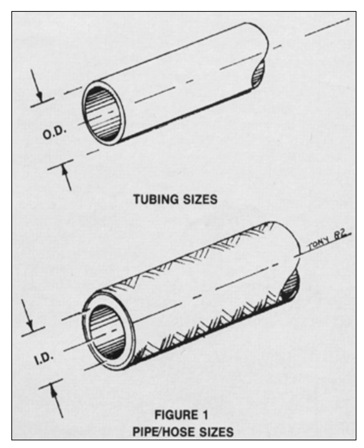What are two types of commonly used fluid lines used in aircraft plumbing? Metal tubing, or flexible hose and fittings. How is metal tubing sized? Outside diameter, wall thickness, in sixteenths. Metal tubing OD, outside diameter.